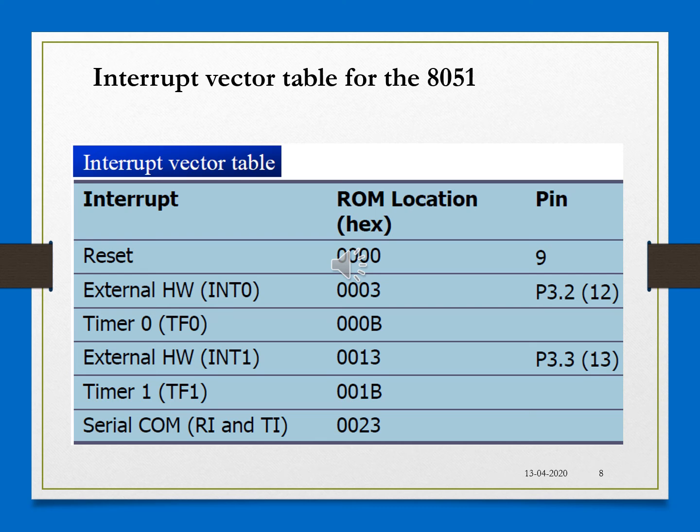And if you recall, all our programs, what we write, also start from 0000 location, isn't it? And if you observe the vector table here, the beginning location starting from 0002 to 23H or 25H memory location is exclusively saved for interrupt service routines, or the vector table. It is allocated for these interrupt service routines. So whenever we write a program, we are not supposed to use these locations.